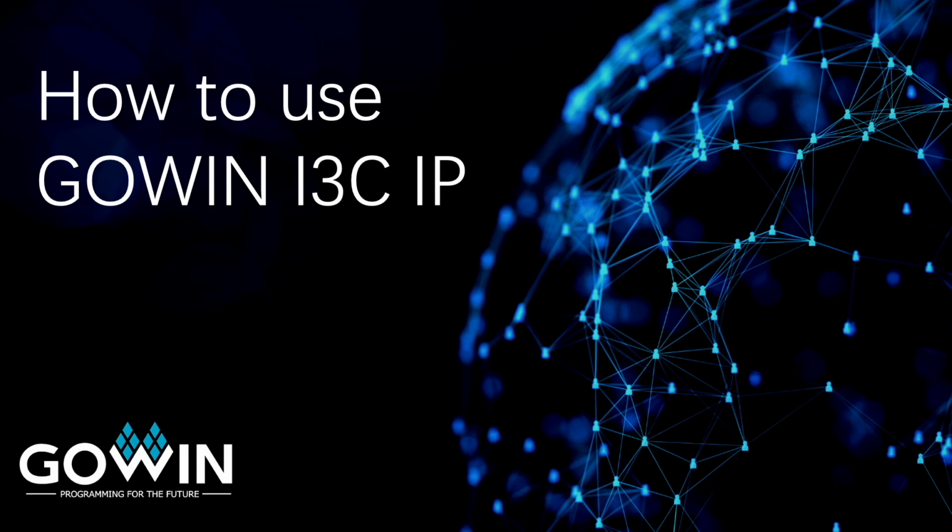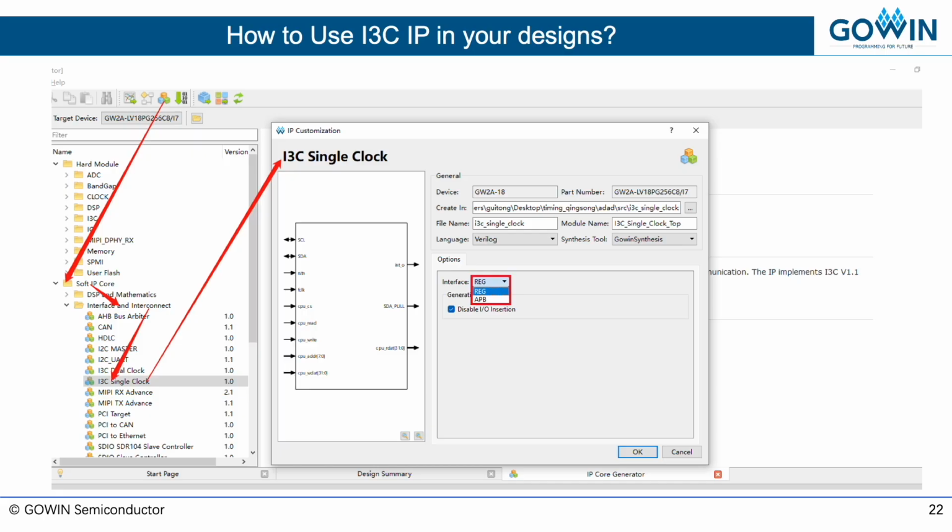First thing you'll be doing is making sure that you pick the right device in terms of the resources, that is number of LUTs and registers. Keep in mind that these GOWIN I3C IPs utilize about 2.2K LUTs and 1.5K registers. Make sure you account for these resources when you choose the FPGA for your design.